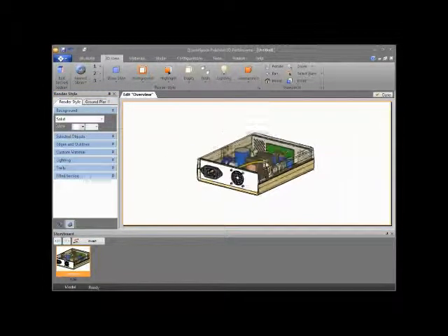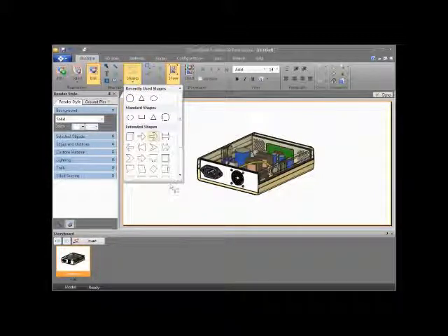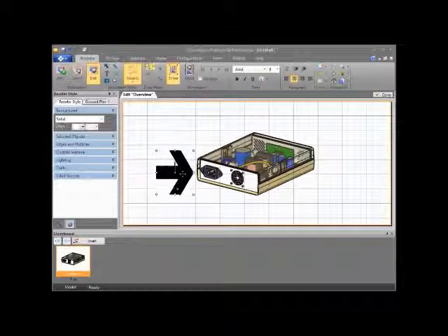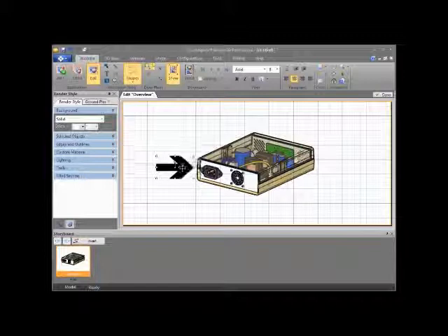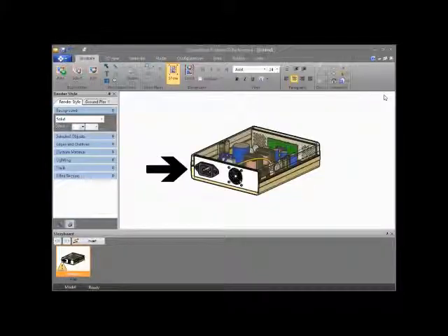And then the other thing that you would want to do probably with your scene is to add a markup layer to it. So each illustration can capture a set of markups, a 2D plane, or you can actually draw those into the 3D plane. Let's just go ahead and quickly add like an over plane arrow here or something, just to demonstrate how the markups work. So you basically just pick a markup and drag that out to your scene. Place it here. We could change the color. I'll just leave it black for now. And when you're done, what you'll get is a scene that you've actually captured here. And this button right here, or the storyboard now shows it down here as your first illustration.